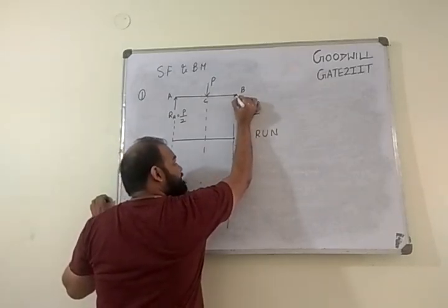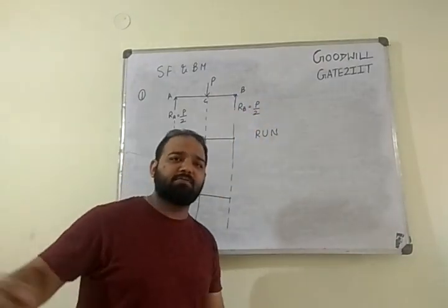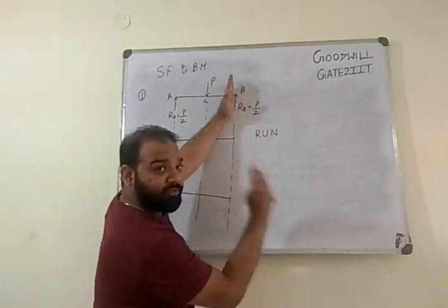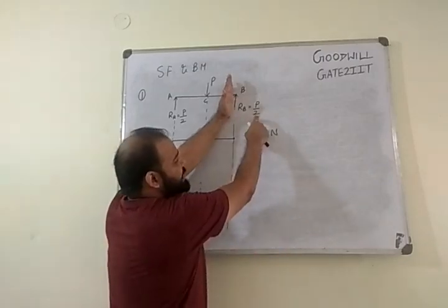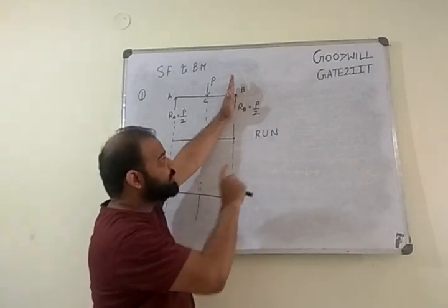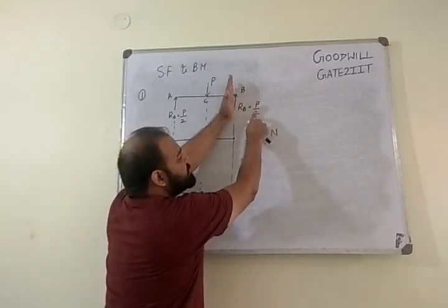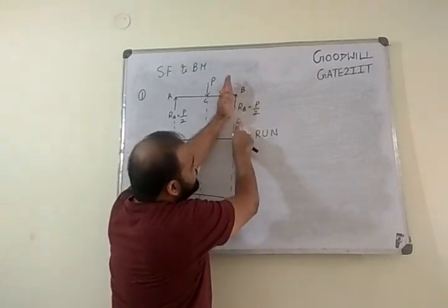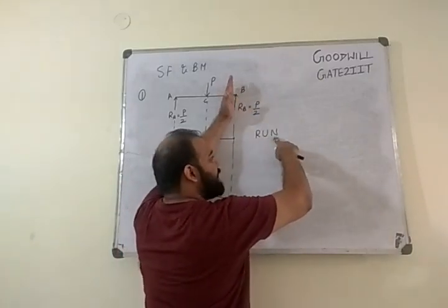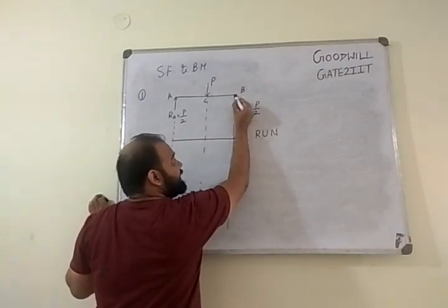Now, we were at point B. Now I'm coming a very small distance to the left hand side of B. Very small distance, let's say 0.000001 mm. Now you are slightly on the left hand side. See what force you have on the right hand side. So the force we have on the right hand side is what? P by 2 now. Correct, right? Again I'm repeating, don't see anything on the left hand side. P by 2 is the force on the right hand side. Now this is an upward force, right, upward. So I should mark this force as negative in my diagram. So what should I do? I am slightly on the left hand side.